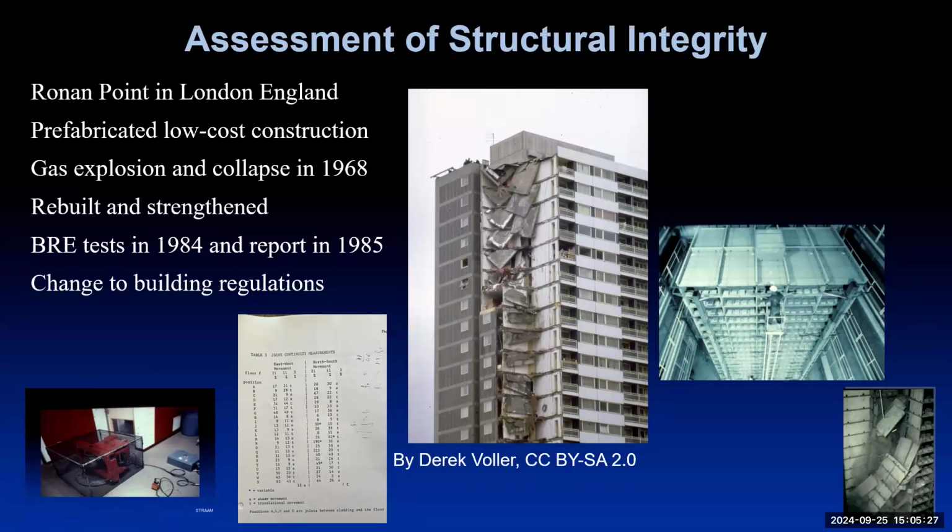And the laboratory was that of building a 1/4 scale of Ronan Point. And to do that, this is what signifies one of the problems that you've got here. If you have 1/4 scale, then the mass that you're using in the building actually decreases by not 1/4, but 1/4 cubed. So you've got to put extra masses in the structure.